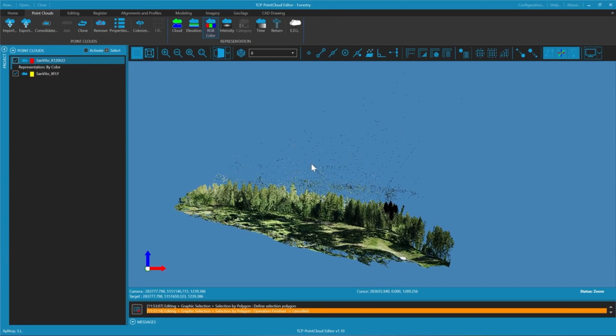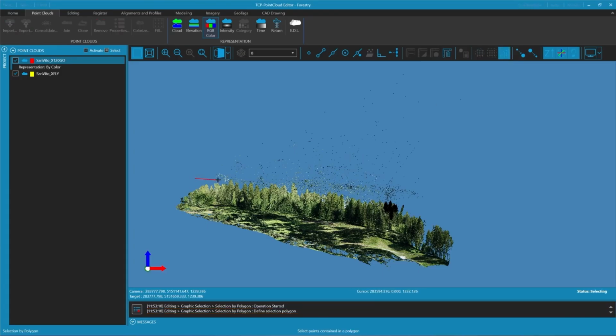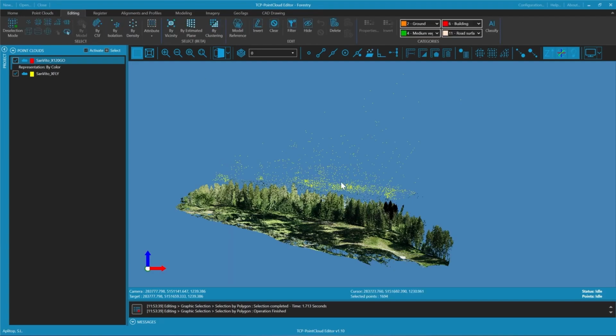First thing we're going to do is get rid of all the points that we know for sure that we don't need. So these top points of noise, we can just zoom a little bit and make a broad selection, taking care of not selecting any of the actual point cloud so as not to lose any detail. And all of that noise, we directly remove those points. So that's the way the application works.